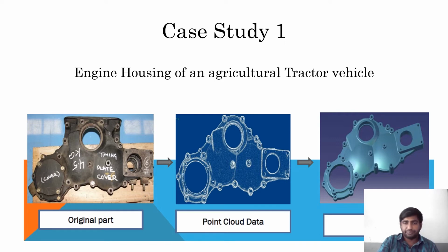So here we are going to use some 3D scanner or CMM to measure the cloud points. After capturing the cloud points, it will be transferred into any CAD software. After that, the CAD model will be created, and you know the remaining part.